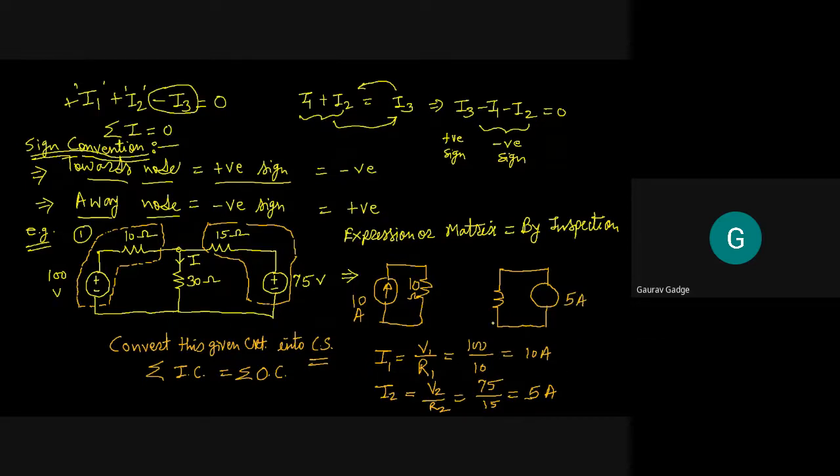Now we have to again decide the direction of the current source. Can you tell me that direction? The direction of that current source, based on the positive polarity in that voltage source, is to be upward. What should be the value of the internal resistance of the current source? It should be the same as the internal resistance of the voltage source, that is 15 ohms. Now what is left in the circuit? The only part left is a resistance of 30 ohms.